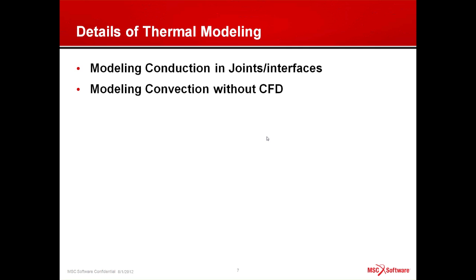Modeling convection without going to a full CFD code, because Sinda runs in tens of seconds or minutes and occasionally may go for hours, but usually it's more like minutes or tens of minutes, where CFD codes go in hours, tens of hours, or even days, and are very slow. And with CFD, it's very hard to test verify a model, to adjust the convection to get a test in a lab to agree with your model if you need to test verify it and adjust things, because you kind of get what you get as far as the convection, where when you're using your own convection correlations, you can adjust those to help get a test verified model.